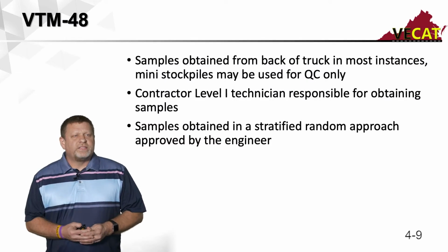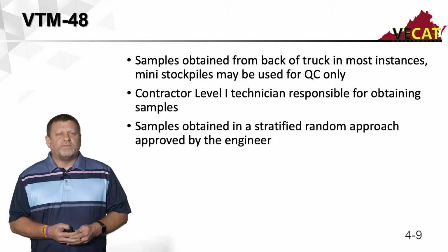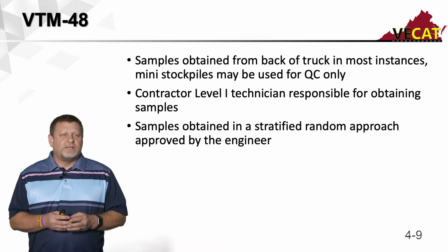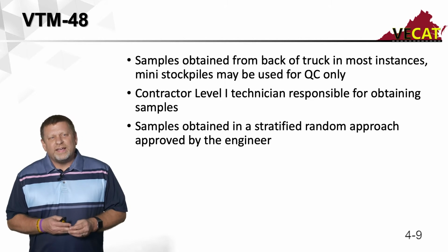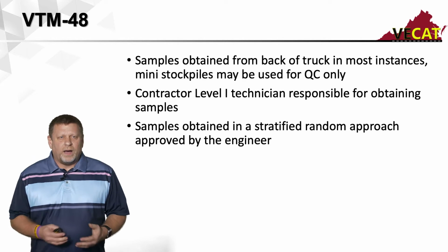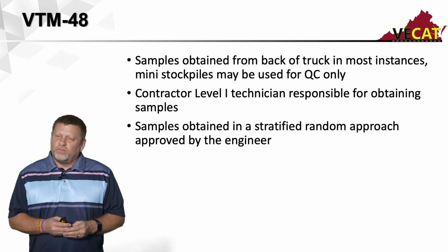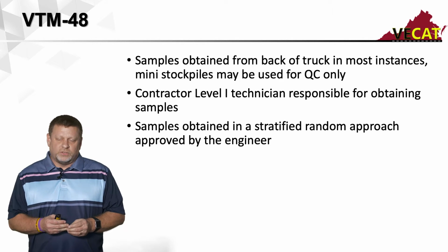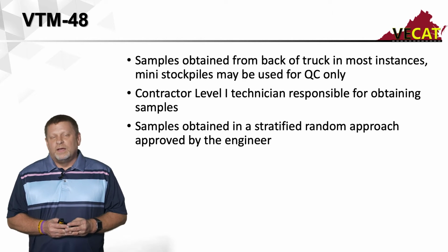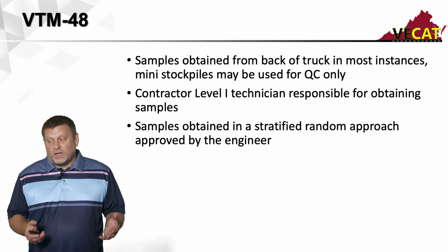Now let's continue with VTM 48. Samples are obtained from the back of the truck. In some instances, there are cases where you might want to use a mini stockpile to take a sample. As far as the producer goes, that would only be for QC purposes. It wouldn't be for assurance or acceptance or anything like that.